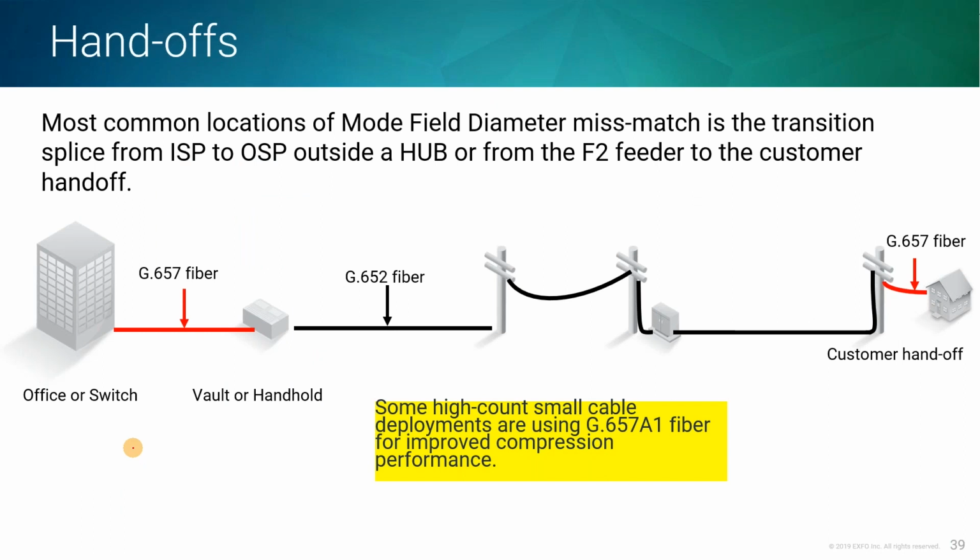This is typically where it happens. We are seeing G.657 in OSP glass. To get these large 864s and 1728s, some of the manufacturers have switched to bend insensitive, because the big challenge was never putting a lot of fibers into a cable. It was putting a lot of fibers into a cable that fit into existing duct structures. We're not going to replace all these duct structures. So they've done a lot with trying to get the fiber into smaller and smaller cables.